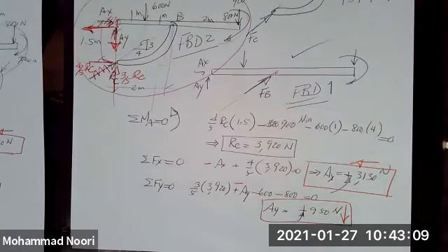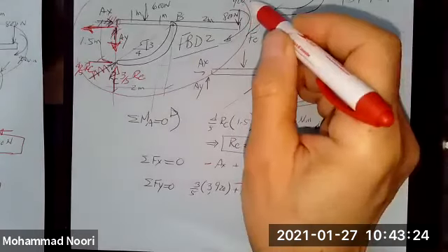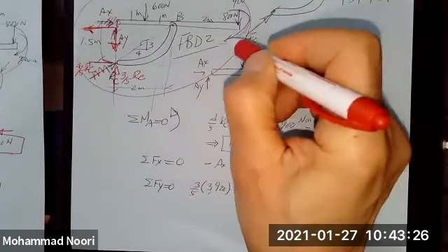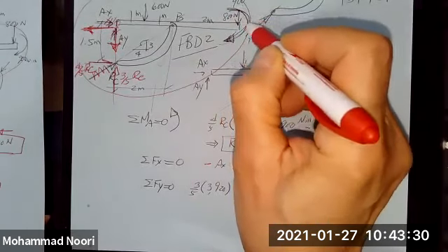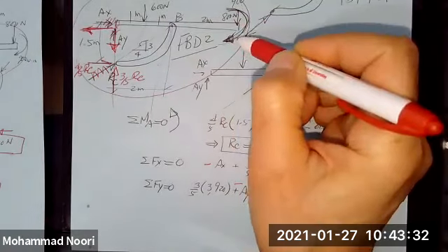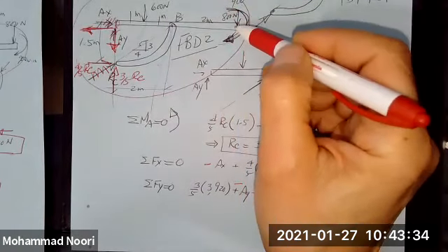Any questions? I have a question. Please. So in the free body diagram, what is the difference between the 800 Newton force and the 900 Newton meter force? Oh, this is not a Newton force. This is a 900 Newton meter moment. This is an applied moment, like a couple. It's a free moment that you put here.